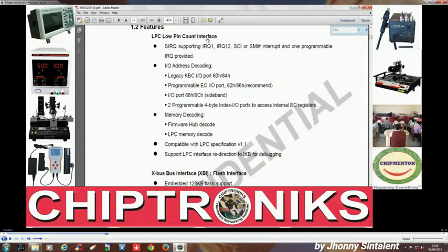There must be a mechanism to transmit this data, because CPUs are all man-made. They don't have intelligence. They can't see anything. So there must be an intelligence involved which differentiates between my pressing a touchpad and my pressing a keyboard, and here is this intelligence. IRQ1 is generated by the IO controller when a key is pressed, and IRQ12 is generated by the IO controller when a touchpad is pressed. We will understand all of these things while going ahead.